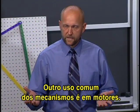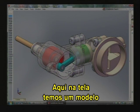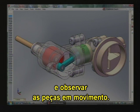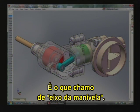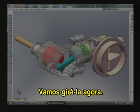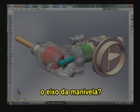Another very common use of mechanisms is in engines. Here on the computer screen, we have a model of a compressed air engine, and it's all color-coded so that we can talk about the pieces and keep track of all the moving parts. Let me start with this red piece here on the left. That's what I call a crankshaft. The red piece is mounted up in the case of the engine on a bearing here, so it can rotate about this point right at the center. Let me cause that rotation now by dragging on it. See the rotation of the red part of the crankshaft?